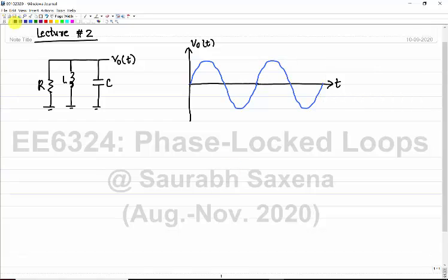So this particular signal V out of t, if I say that the amplitude is +1, is nothing but sine of omega naught t, where omega naught is equal to 1 by root LC for a given LC circuit. Is this part clear? If this LC circuit produces a sine wave with such an output waveform, then it can serve as a clock to my system.